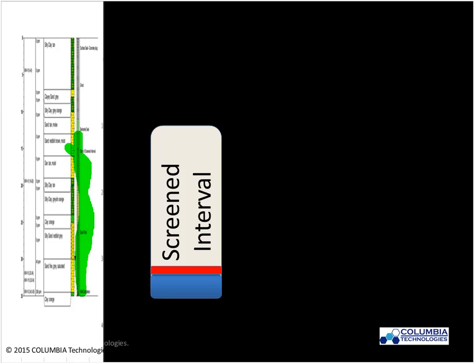I think that's a common challenge that we run into in the industry, is we have these long monitoring well screens, but they're bridging across a lot of different transport zones and storage zones. And so this is the result of the most recent sounding of the well. So we've got air down to here. So here's our oil interface. We've got our nice air, oil, and water. So in the well, we have that nice traditional oil floating on water. And so we've got a little bit of water in the bottom of the well and a little bit of LNAPL.